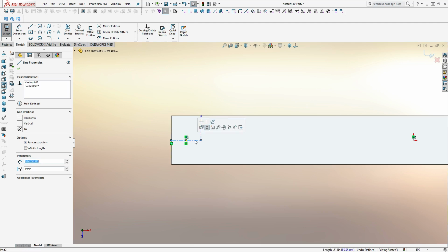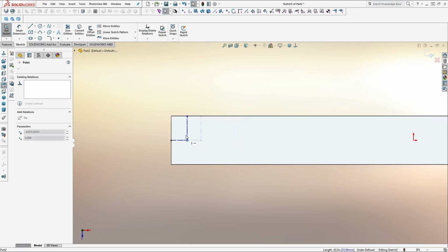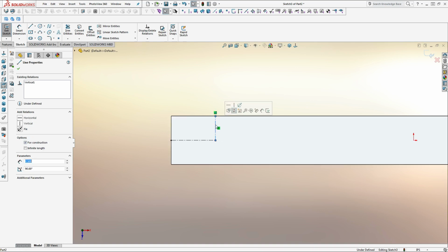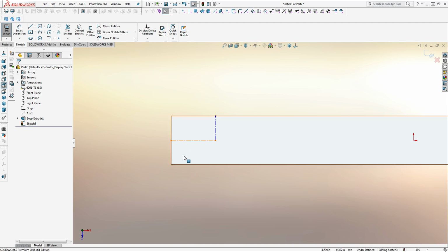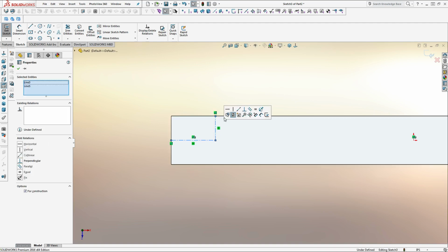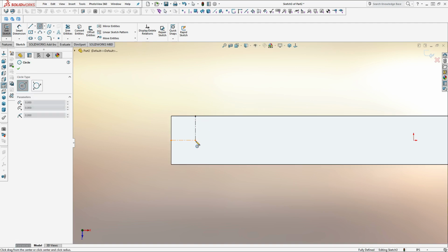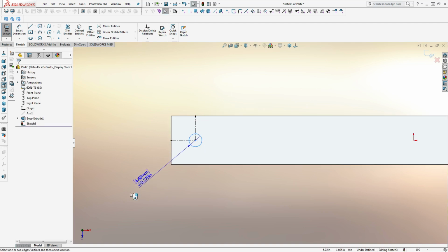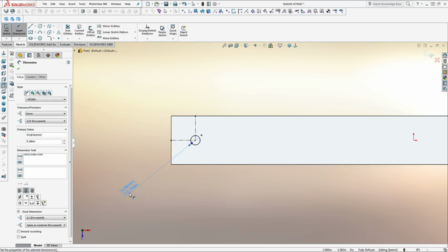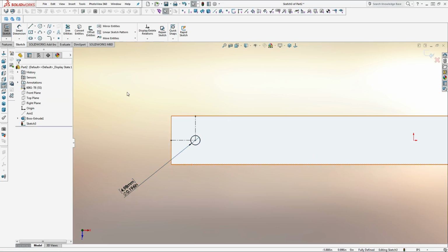And this line length, the selected one, is my x-axis, and that's undefined right now. However, if I connect this, that's rigidly defined. My y is going to be half because I'm currently halfway through a 1 inch. So if I set these two equal, it creates a point that's fully defined where I can set up my hole and go from there. So that's an easy way to do it.